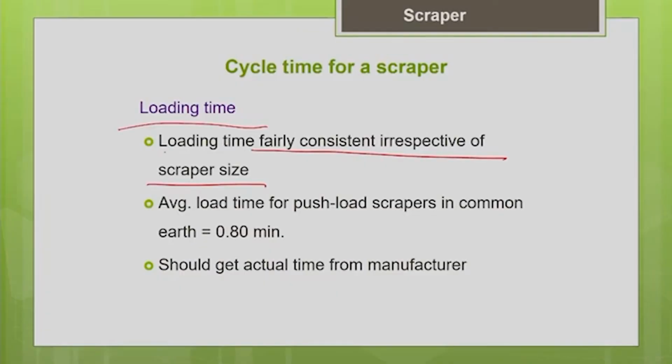According to the size of the scraper, you have to select the compatible size of the pusher, and we are going to supplement the loading power. So that is why the loading time is fairly consistent irrespective of the scraper size. Whether it is a smaller one or bigger one, since it is assisted with the pusher, the loading time won't change much.